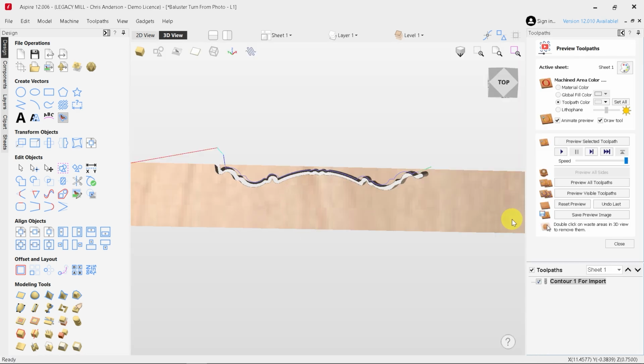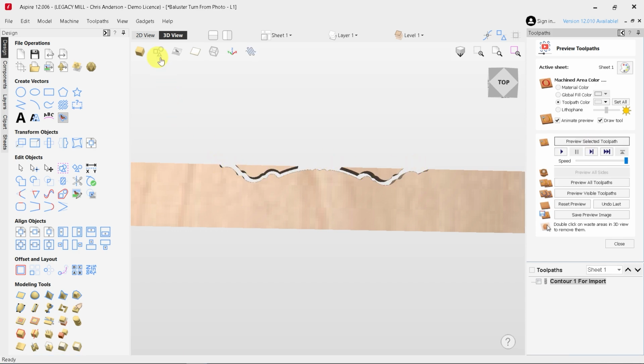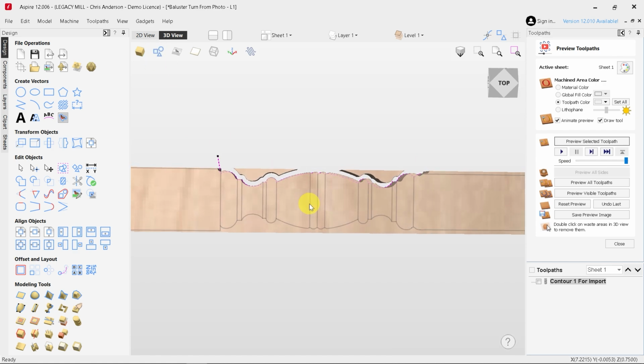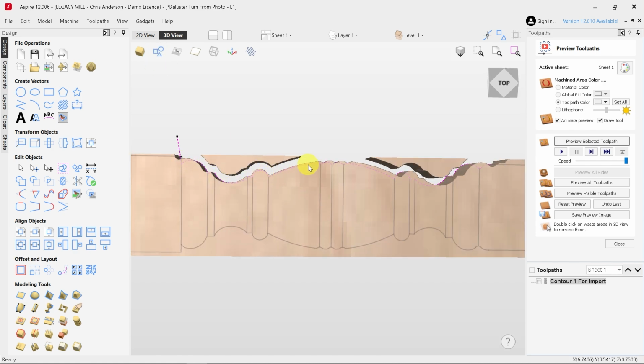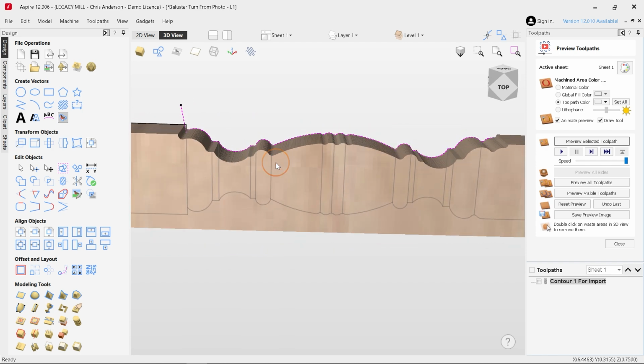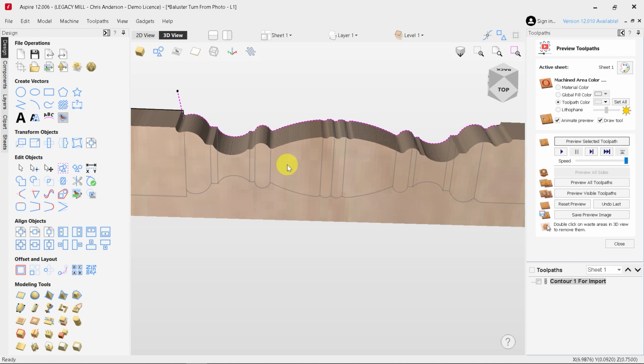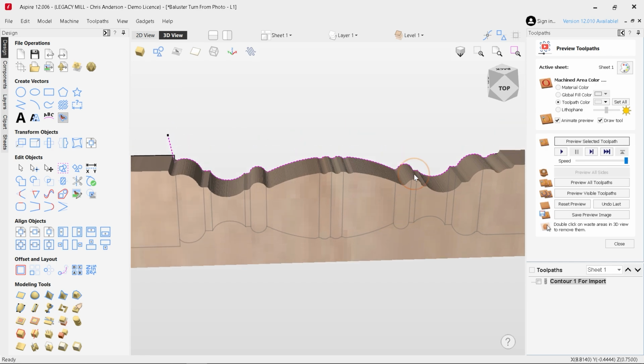So now that we've generated our toolpath, we can actually simulate it just to see what it does. It follows from left to right. We can even turn on our vectors here, and you can see it follows that line beautifully right along the top, giving us that result. You can delete these if you wanted to. This is really a side cut, because it's the 3-axis side cut. But this will be converted in Conversational CAM to cut from the top using these parameters, which is really cool.